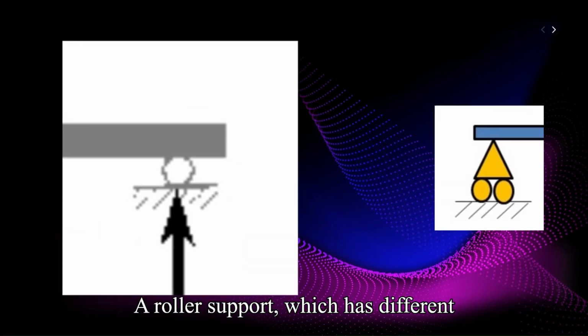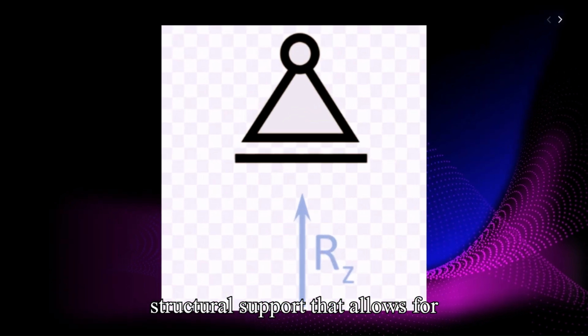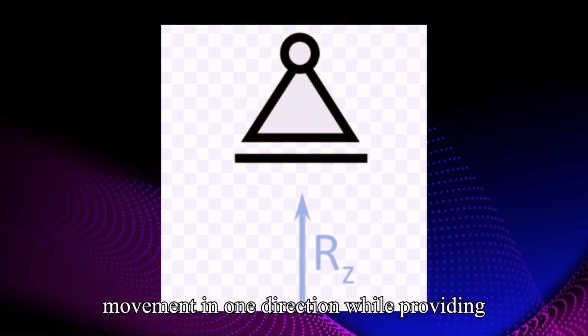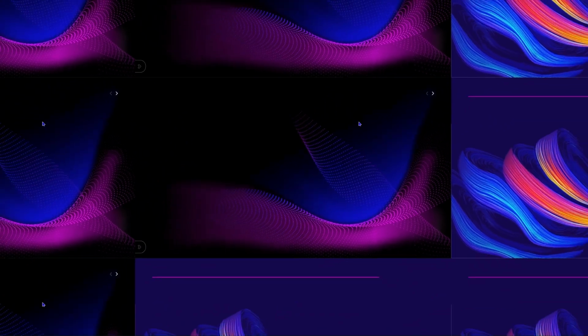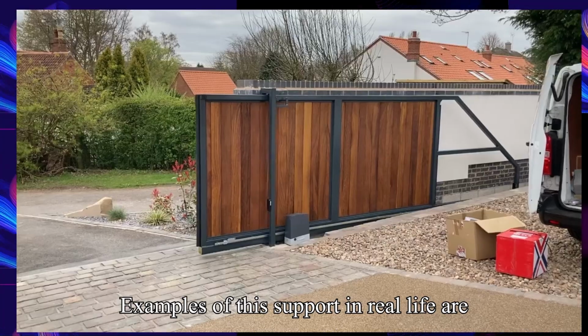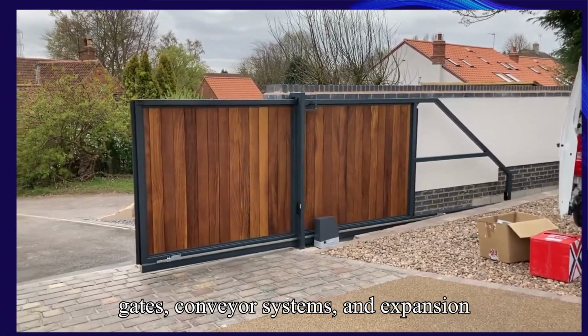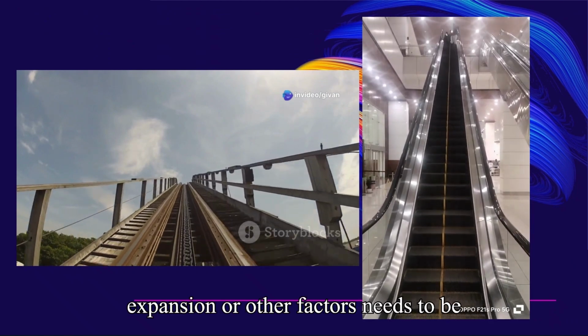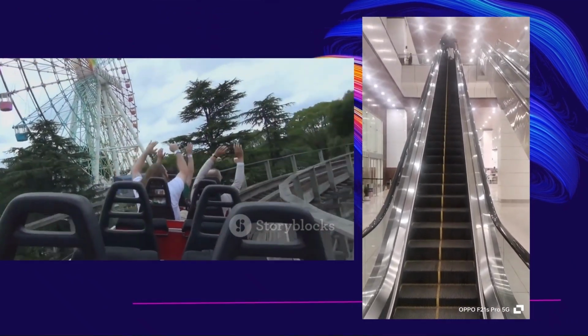A roller support, which has different representations on paper, is a type of structural support that allows for movement in one direction while providing vertical support, according to the plane of reference. Examples of this support in real life are found in structures like bridges, rolling gates, conveyor systems, and expansion joints where movement due to thermal expansion or other factors needs to be accommodated while maintaining stability.